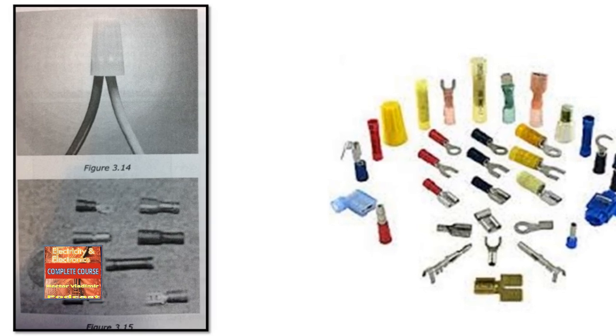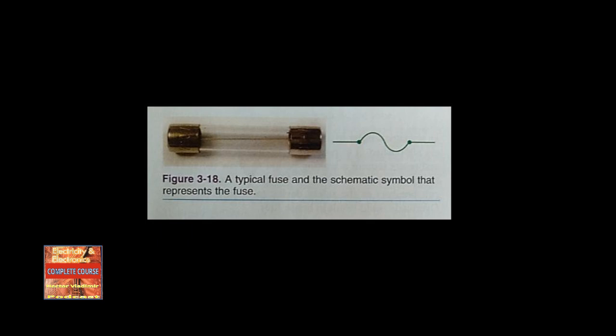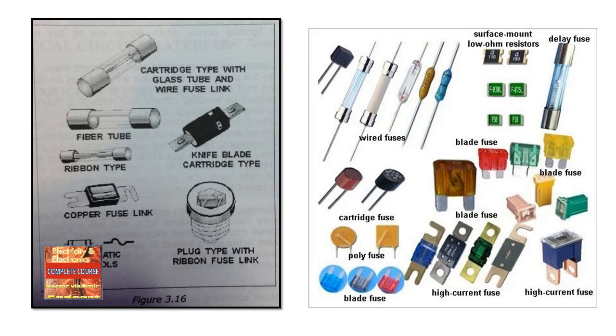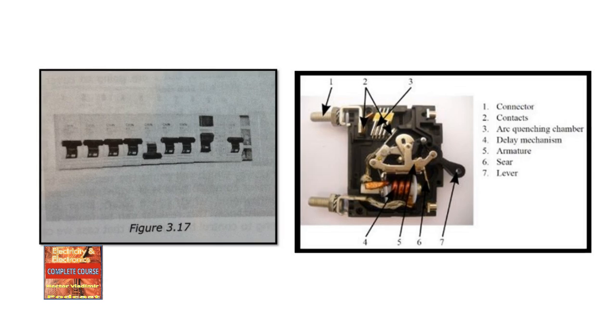Once the circuit is built, we must protect the equipment and or components because of shorts, grounds, and opens. The protection devices you will need to familiarize yourself with are fuses and circuit breakers. There are others out there, but these two are in every electrical circuit around. Fuses, figure 3.16, provide short circuit protection and are rated by voltage and current capacity. If a fuse is rated for 6 amps and current exceeds 6 amps, the fuse will open or blow to prevent damage to other electronic or electrical components. Circuit breakers, figure 3.17, are used to protect a circuit from overloads and shorts and are resettable components.